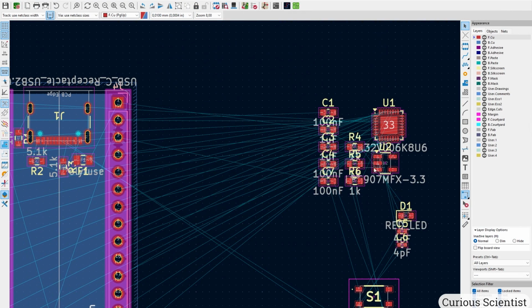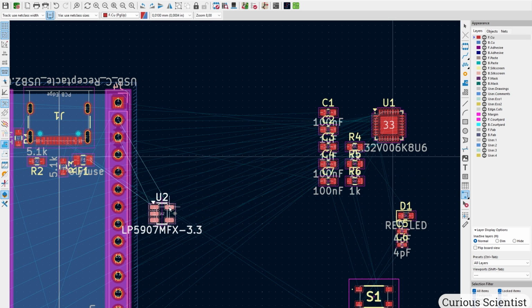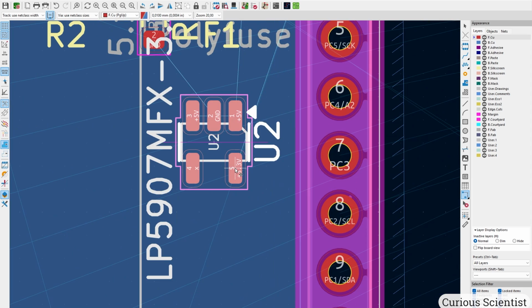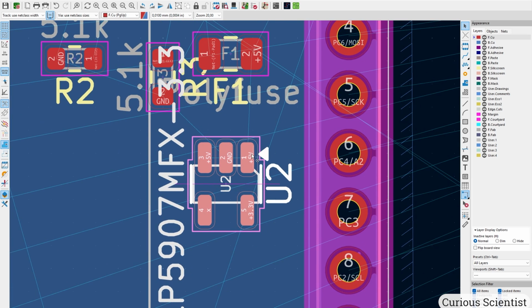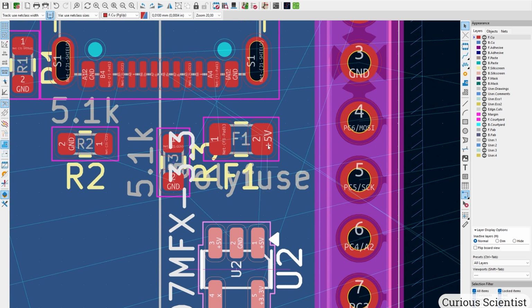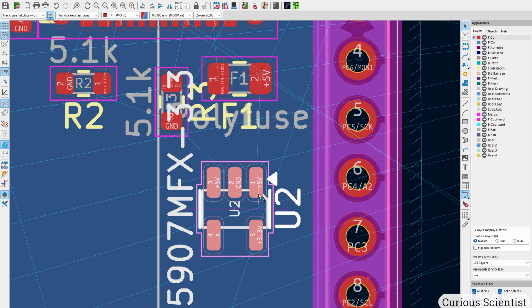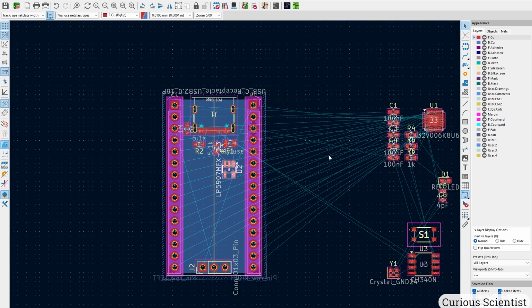And then the next step could be the voltage regulator. So the voltage regulator has its chip, and I rotate it like this because after the fuse, we have the 5 volt coming out from the fuse, and that has to go to these pins. So it would not make sense to put it sideways or something like this. But both of the 5 volt pins, one is the input voltage and the other is the enable pin, have to face here because it's just more convenient to place them like this.